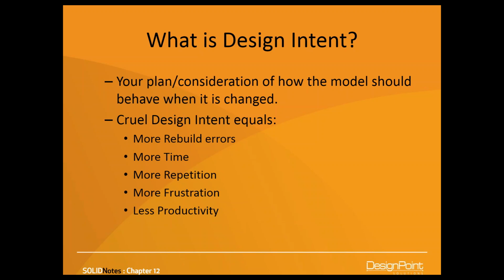Bad design intent practices can be tremendously painful to you later on down the road. Most of the time, you create a model, and there's about an 80% chance that you'll have to re-edit that model at some point in time.